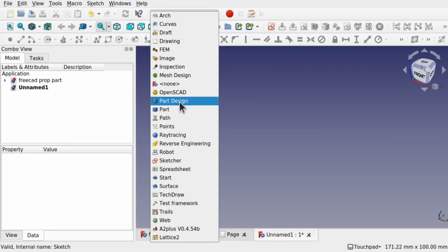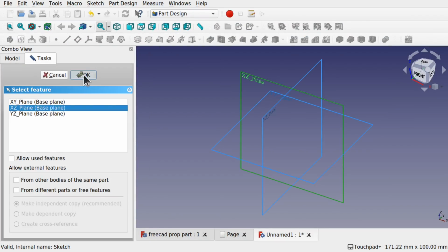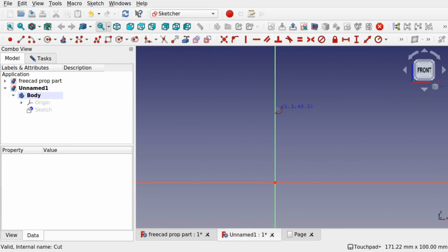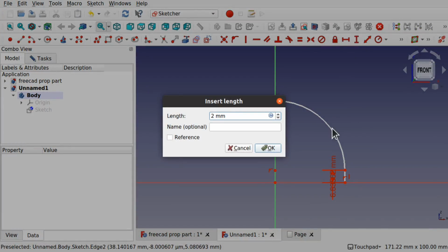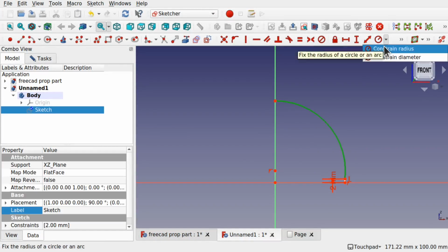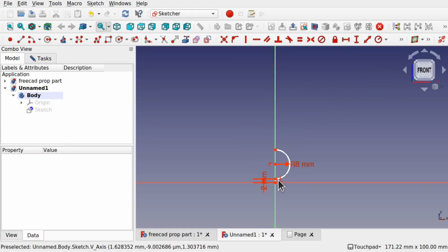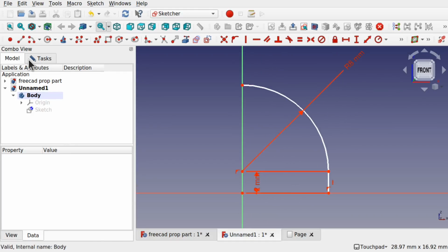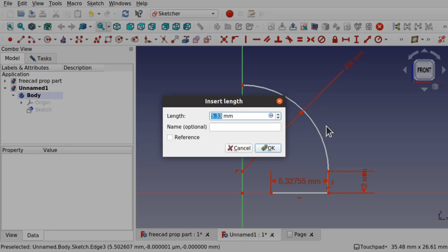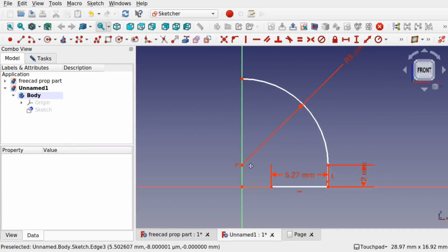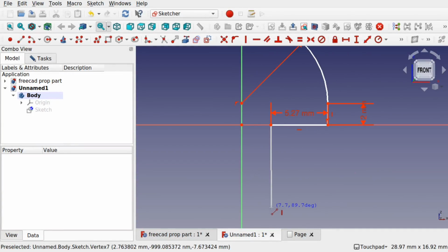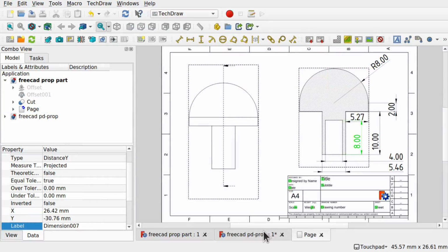We'll first start in the part design and we'll create a sketch along one of the planes, and we could be using simple geometry in there such as arcs, lines, polylines, etc. We basically work our way down through the technical drawing to create a profile of the object. And all we need to do is just do one single action upon here. So we're not going to be pad or pocketing. What we're going to do is create a revolve.